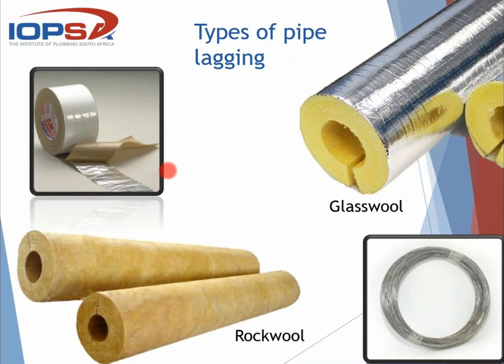As you can see here, these two examples have one single split. You open it up slightly and you put it over the pipe. With rock wool, you go onto the website, have a look, and they will say to use binding wire every 20 centimeters or so, tie it off, and if you like, you can wrap it up if it's outside. Once you've bound it like that, others come with aluminium foil around it, which is already protected, and you could use this sort of sealing tape. Some even come with a taped strip which has a peel-back backing, an overlapping piece of tape which you peel the backing off, and it's a self-sealing system, and that's reasonably common here.